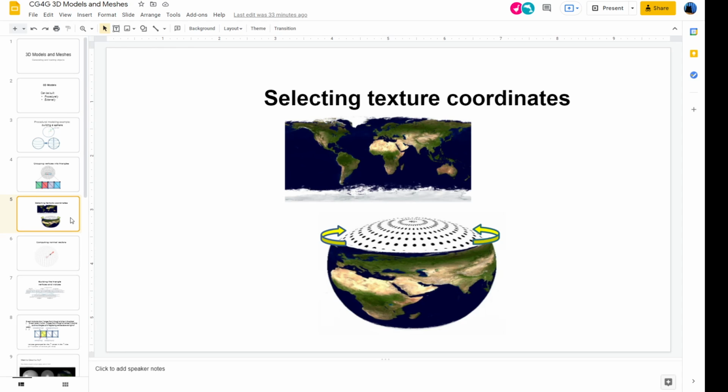This was index number 1, index number 2, index number 3, all the way around like we had in our models. Do you join it to itself, or do you create a non-watertight version, in which case you have something that's hopefully at the same location, maybe it is, maybe it's not, but it's at 1.0, right, as it goes all the way around. Because 1.0 and 0, in the case of a circle or these sorts of calculations, wind up being at the same location. Why is that an issue? Well, for watertight models, it's great to avoid that extra one and just have it join back to itself.